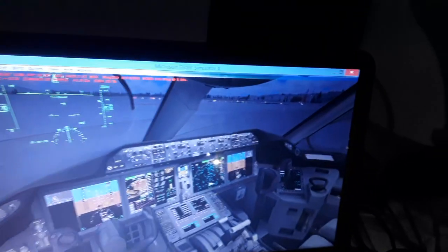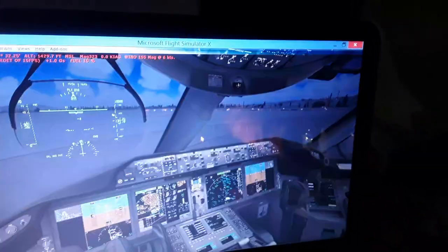Also the temperature of the air becomes freezing, minus 20, minus 30, minus 40, minus 50, minus 60 degrees below 0 Celsius. So we're gonna have a different fuel mixture request every second, which is adjusted automatically from the FADEC, because we have higher intake also of air from the front fans as we fly faster, and a thinner air. So it's a good thing to have the FADEC installed into your engines to do the fuel mixture adjustment also as we descend back to the sea level.